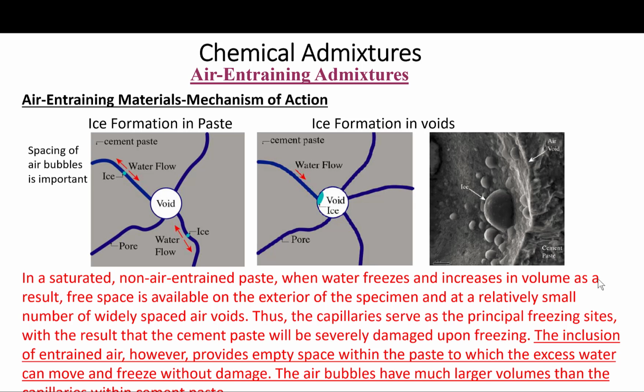I will talk about this during durability, but I'm mentioning it here just for early reference, as far as how these air bubbles protect the paste and the concrete from the effect of freezing and thawing, and how they provide sites for the expansion of the ice during freezing, in order to prevent this expanding ice from cracking the concrete.